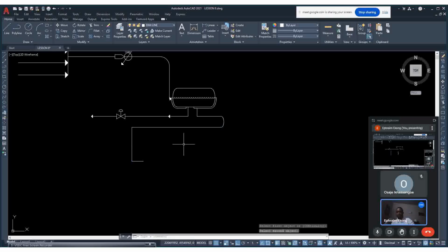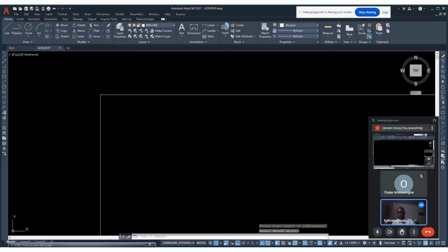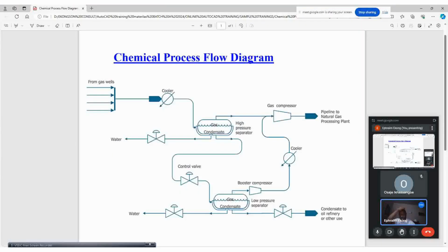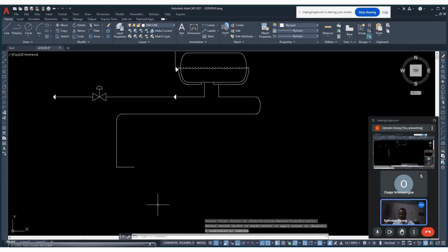Okay, so it's not working. So you go to fillet, click on fillet, type the radius, enter, you type 400, enter. Click close this edge and click close this edge. So 400 seems to be small. We undo, Control Z, go to fillet, type R, enter, and type 700, and press enter. You click at this point, and you click at this point. Okay, that's it. Perfect.